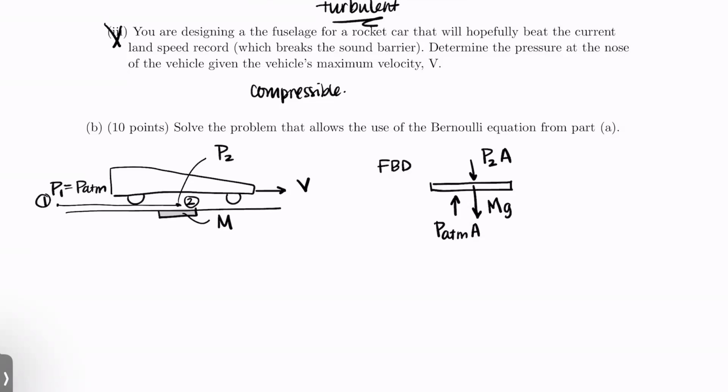Right? So this is going to lift when the pressure on the bottom overcomes the pressure on the top and the weight. So when P atmosphere times A is greater than P2 times A plus mg. That makes sense? Okie dokie.